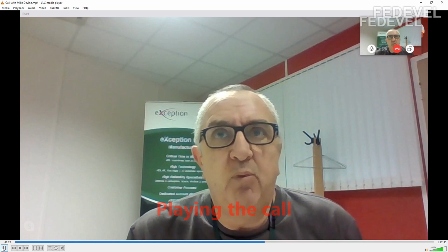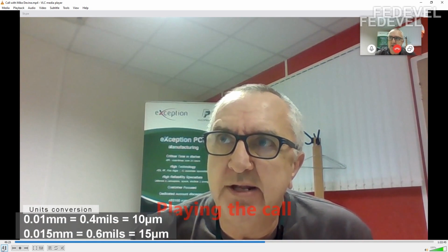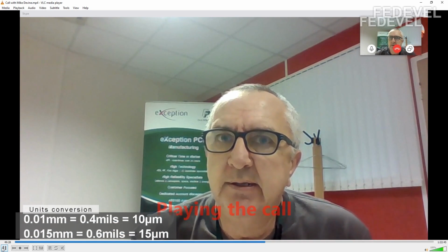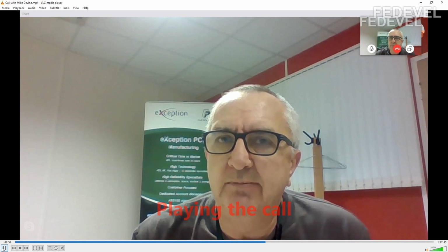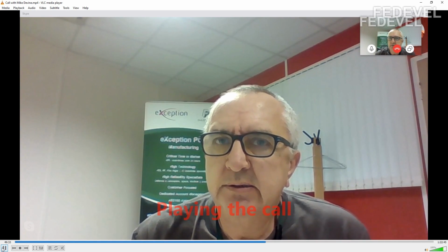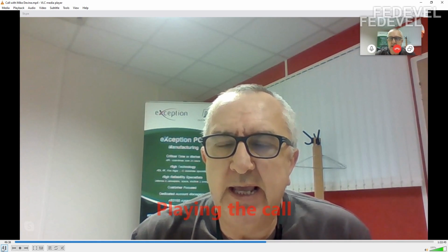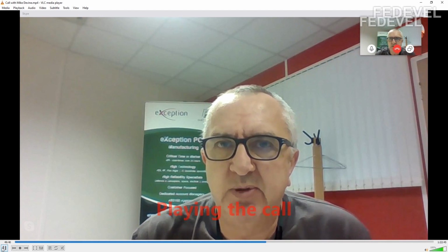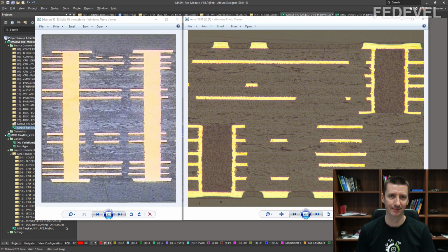No, because you'll end up with somewhere in the region of maybe a 10 to 15 micron dimple where the resin filled holes are. Okay, so copper filled are always better for vias in pad under BGA. It is virtually 100% flat pad surface. And then I had to ask how they actually create these copper filled vias and how they make the surface flat. And Mike will explain in the next clip.